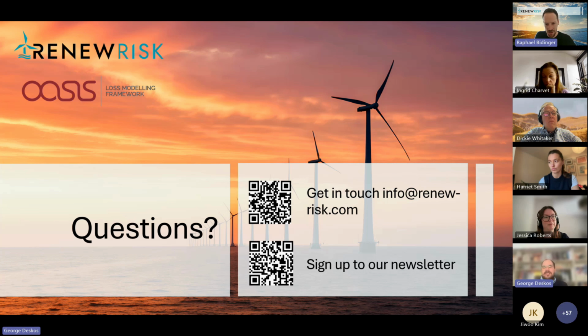I would say that the approach that was taken in B is the one where explicitly each asset was modeled. That means turbines were represented by turbine vulnerability, and cables by cable vulnerability. I think in approach A and C, everything was approximated by a kind of turbine vulnerability function, right?